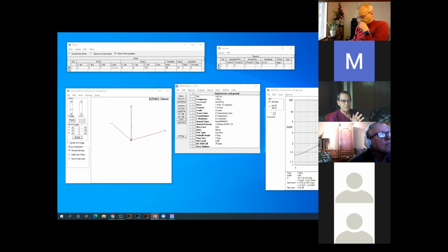Think about it. Now you're going down a hypotenuse, all right? You're going straight down the vertical Z height, so the length of the wire has increased now. Okay, so that forced that change in the wires table apparently. Right, that's going to change your resonant point. If you do that and you redo this SWR, you're going to see your resonant point is way off. You're going to be a lot lower in frequency than you think.